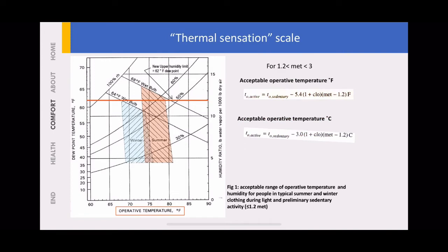Right. So once these votes are collected, they will be compared to the one that you have calculated before in the lecture on psychrometric chart part 1 and part 2. Right. For 1.2 MET to 3 MET, between these two, the metabolic rate of a human being or person that stays inside that room will be superimposed in this comfort zone psychrometric chart.